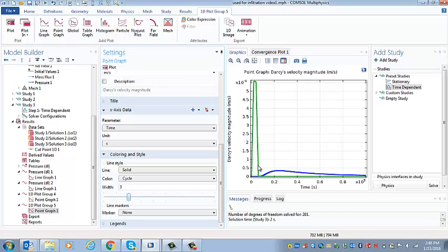So here the green shows the inflow rate. This is the rainfall. You can see it stepping up and then stepping down abruptly. And the blue is the outflow. And so you can see that there's really no outflow at the time the rainfall stops, but that wetting front moves downwards, and the flow starts here and starts to pick up and reaches a peak here after this many seconds, and then slowly tails off. And you can see after the end of a day you still have some outflow. So that, I think, makes sense intuitively, and gives us, actually this would be another data set that we could compare to if we had a way to measure the outflow rate as a function of time.